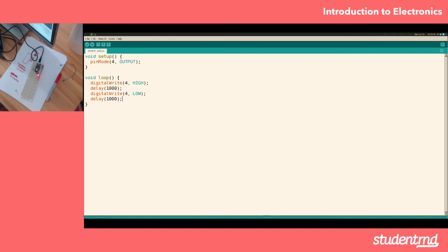What if we wanted to have, so this is what's called a digital port, which means it can only be 1 or 0. We could use these things called analog ports, which would allow us to change the voltage anywhere between 0 to 3.3 volts. So we could actually make it fade in and out. But do we have another way of making it fade in and out? Well, we do, right? We could do it in the microprocessor. But again, these little chips are not anything mysterious. What they actually are is a bunch of individual transistors, resistors, and capacitors made very, very tiny with some very complex infrastructure. But we can just do that ourselves by adding in a capacitor.